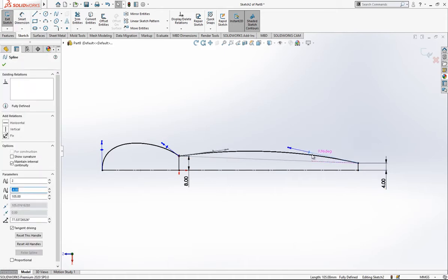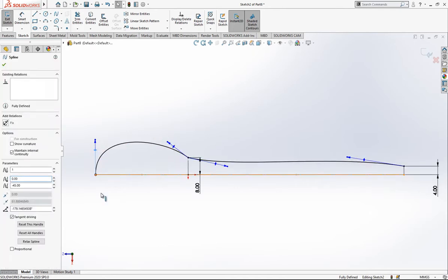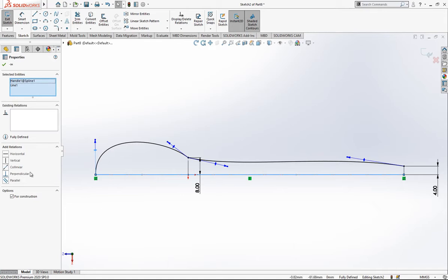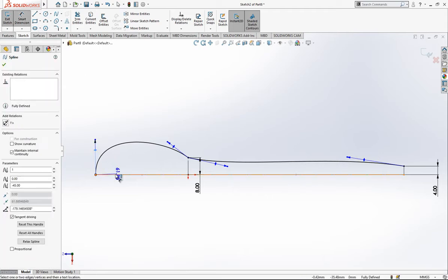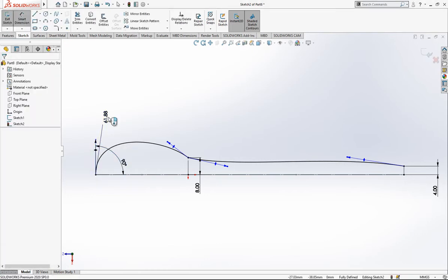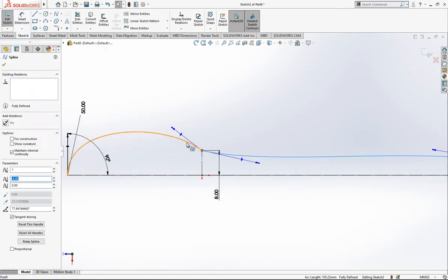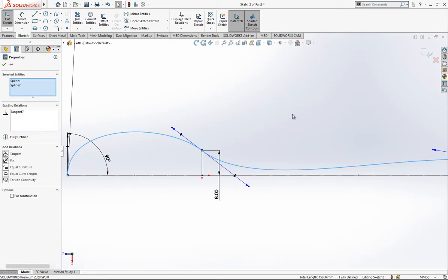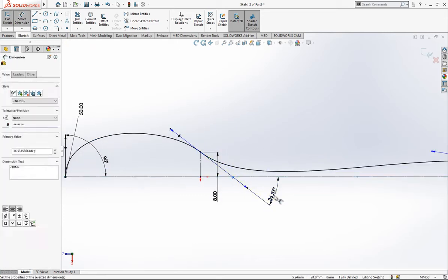And after this operation we will play with the spline with control points. First we press our control and say this spline here will be starting tangent. If you don't want to do that, you can place an angle here, you can say 90, and then the tangency value here 50. After this operation these 2 will be tangent, and we create a 30-degree.